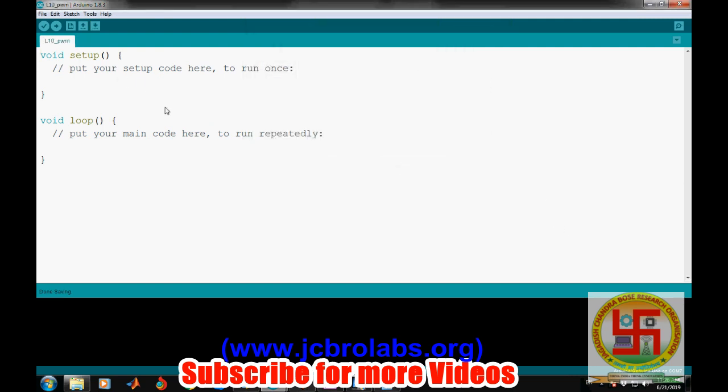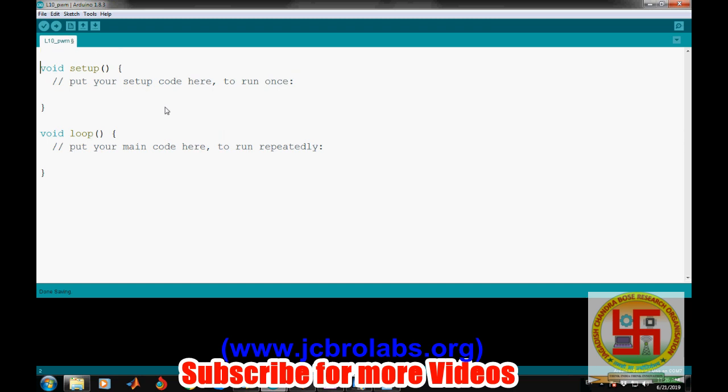So we have saved it as L10. Now we will define a pin mode. The pin mode should be output. We are using pin number 9, so 9 comma OUTPUT, and we'll also be sending the value on the serial port.